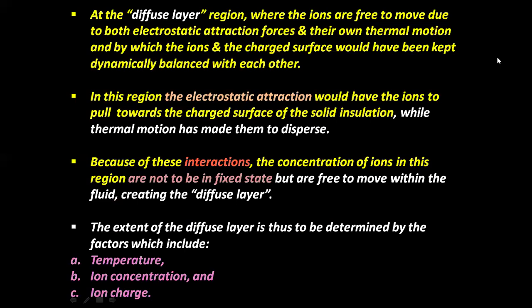In this region, the electrostatic attraction pulls the ions towards the charged surface of the solid insulation, while thermal motion makes them disperse.